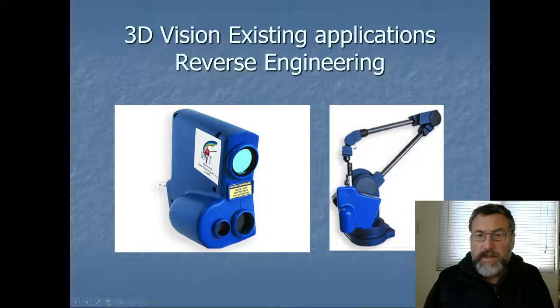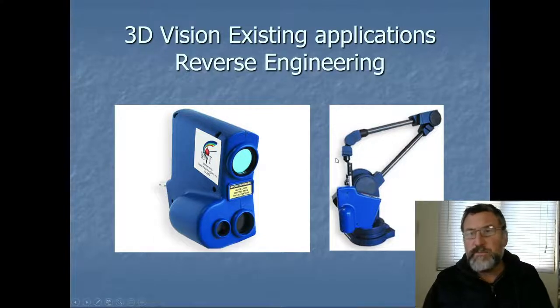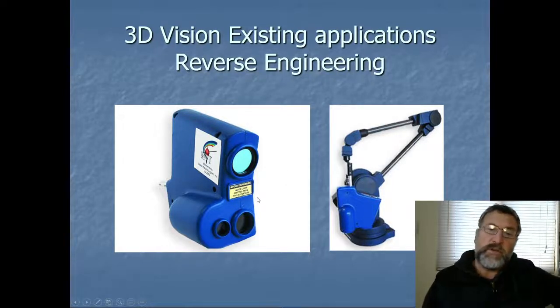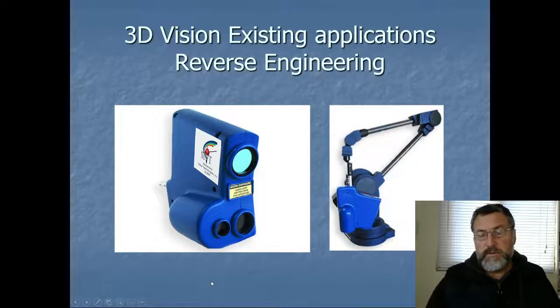Then this is mounted on the end of this precision arm, which is not actually a robot, but each of these revolute joints here has some high precision encoders built in. So it knows the exact position of these rotationary joints here. So it can work out the location of this device relative to the ground coordinate system. And then you can use that to work out the position of all these points on the surface in relation to the sort of ground coordinate system.